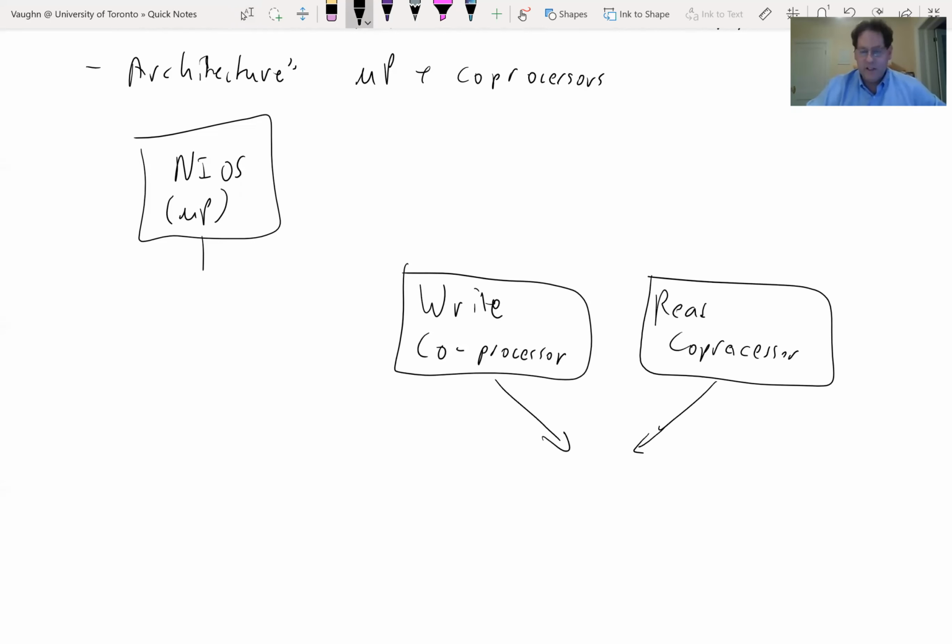They can take control of them, and they can talk to DDR3. So they're wired up right to off-chip memory. They're also wired up to an on-chip bus. Okay, so this was the Avalon bus, but it could just as equivalently be AXI. And by writing to certain addresses on that bus and reading from them, the Nios processor can control the system.